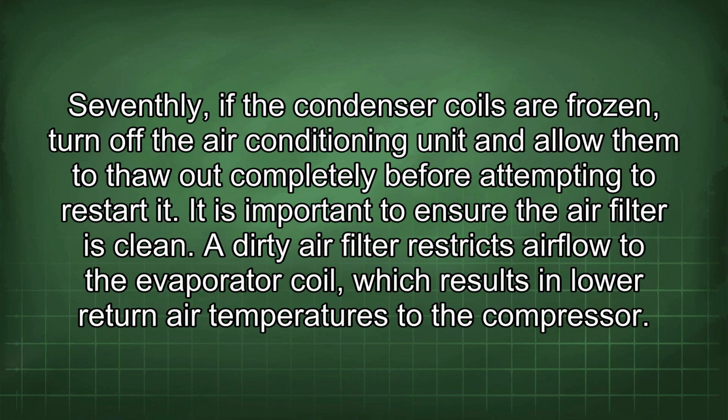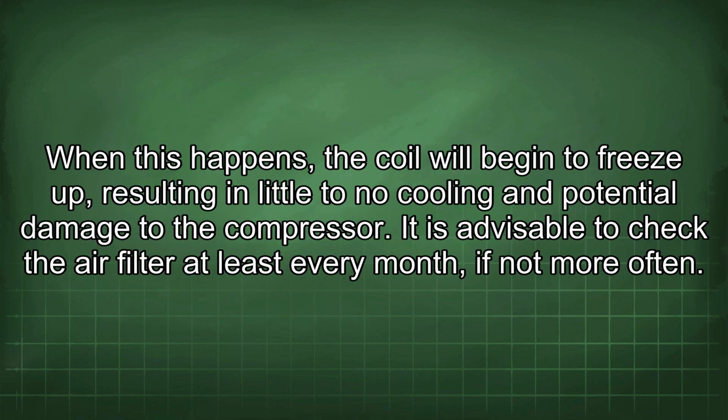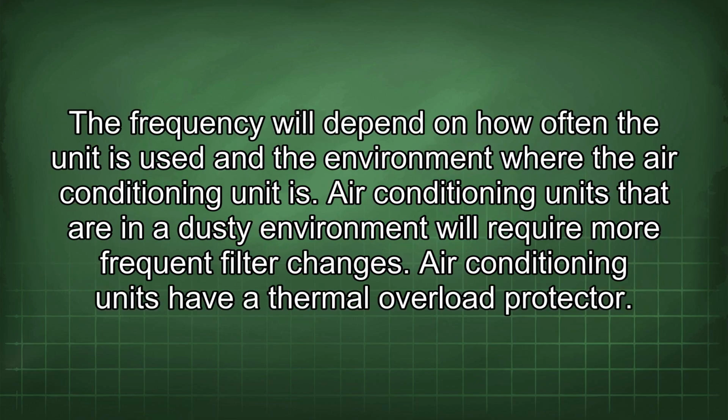It is important to ensure the air filter is clean. A dirty air filter restricts airflow to the evaporator coil, which results in lower return air temperatures to the compressor. When this happens, the coil will begin to freeze up, resulting in little to no cooling and potential damage to the compressor. It is advisable to check the air filter at least every month, if not more often. The frequency will depend on how often the unit is used and the environment where the air conditioning unit is. Air conditioning units that are in a dusty environment will require more frequent filter changes.